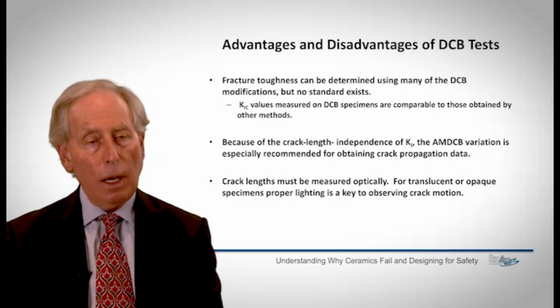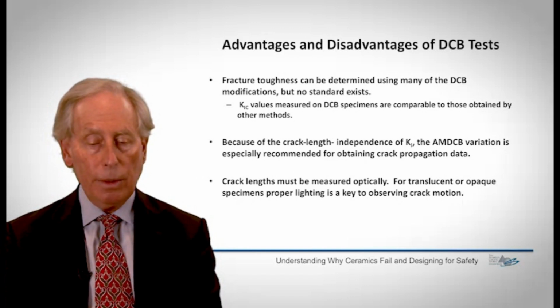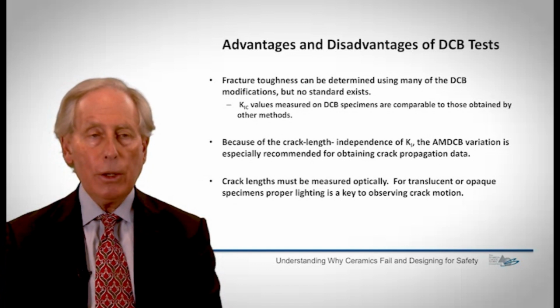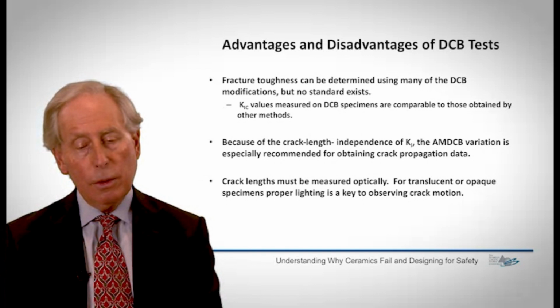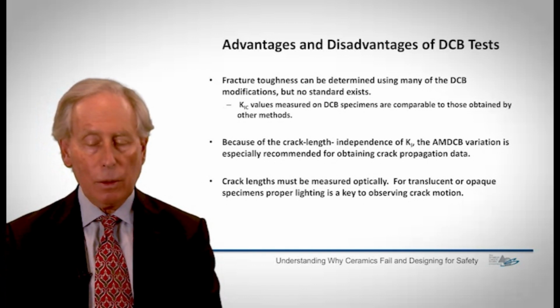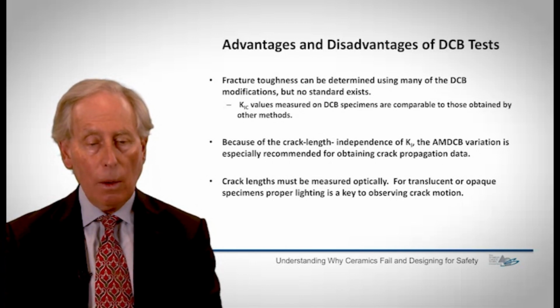One disadvantage of any of these, if you're looking at measuring crack growth as a function of time, is that you have to measure the crack length optically. So for translucent or transparent specimens such as glass, this works quite well. For opaque specimens, you can see the crack growing, but proper lighting is always a key to observing the crack motion.